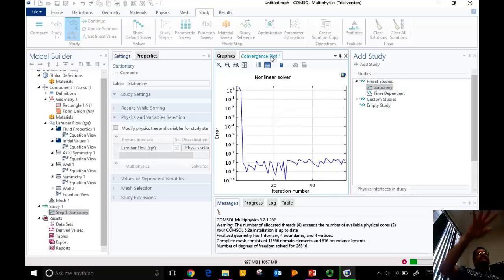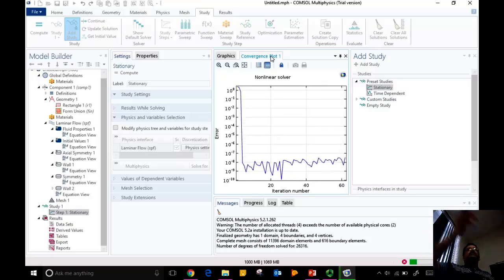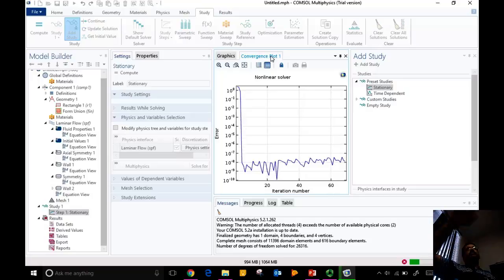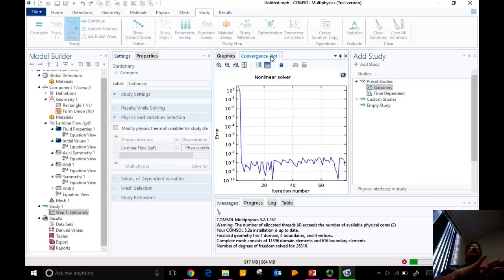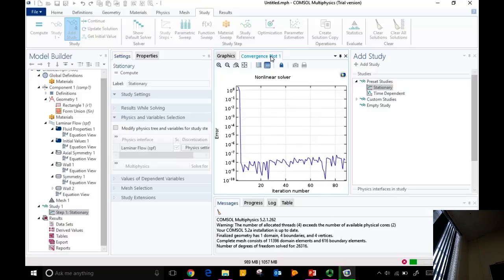On the top surface, you have a free surface, right? So you would have a constant pressure, and then there will be no normal velocity, but there could be a tangential flow. But the tangential stress would be matched on both sides because you have air on one side and water on the other side, right? So that would be equivalent to imposing, for example, mu1 du1/dn is equal to mu2 du2/dn. n is a normal derivative, for example.